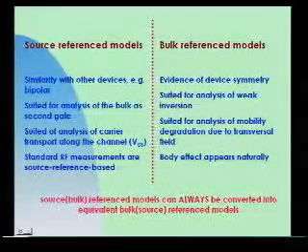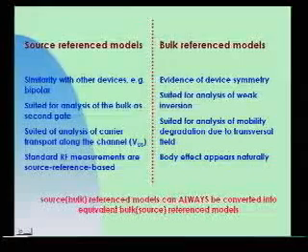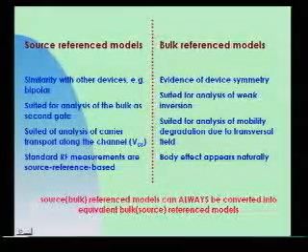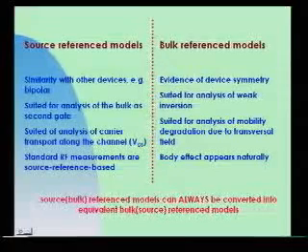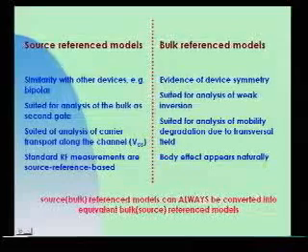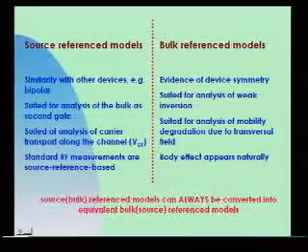It's difficult to consider four terminal devices, isn't it? I never made a measurement in RF, but people told me the equipment is not addressed to four terminal devices. And so, to be consistent, to use a model that is source referenced is better.